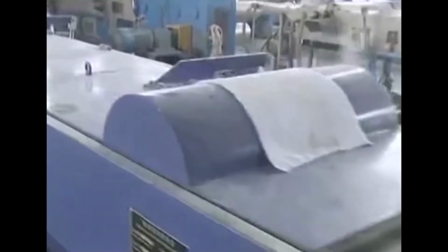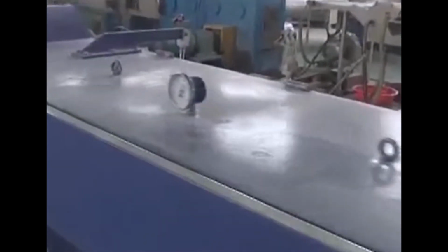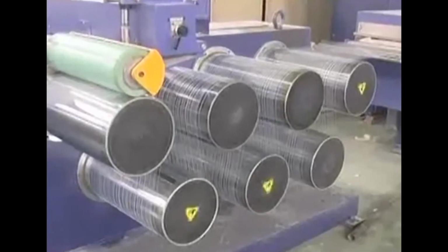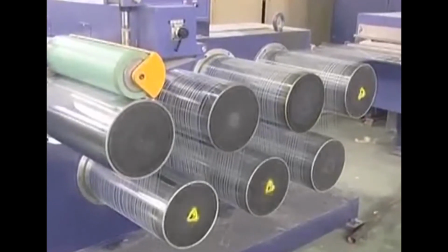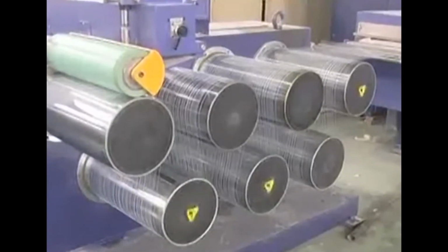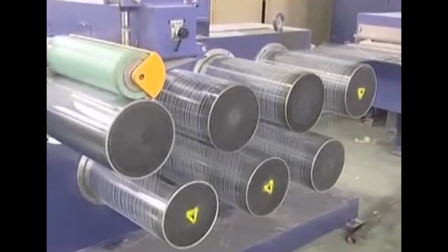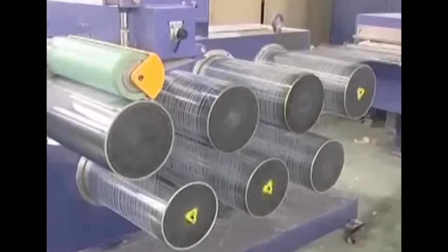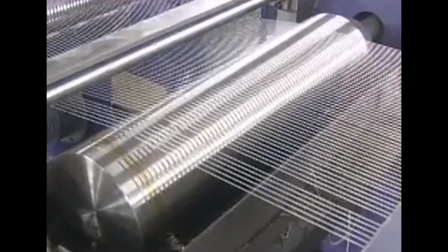And so, after melt spinning, mostly these materials are cold drawn in order to improve the fineness as well as the alignment of these molecular chains to the fiber axis. Usually, it contains two sets of rollers with a difference in speed. The second one always revolves at a higher speed than the first one, usually around 4 times higher speed than the first roller.